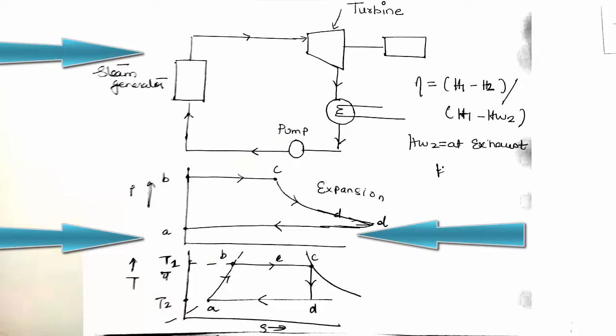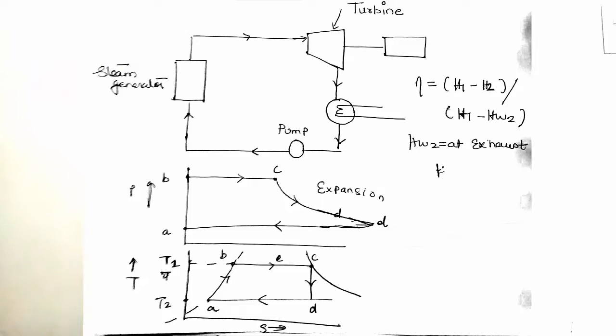So you can use those gases directly, or you can use those gases to heat water. Inside the boiler you will have tubes, and water flows through those tubes. When the gases at high temperature and high pressure come in contact with the tubes of the boiler, they heat this water to a higher temperature and pressure. So it is converted from liquid water to gaseous form, and it is known as steam.